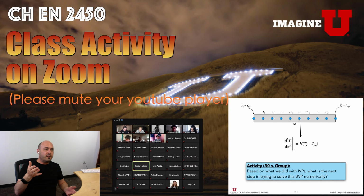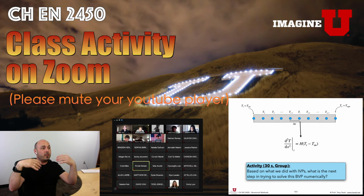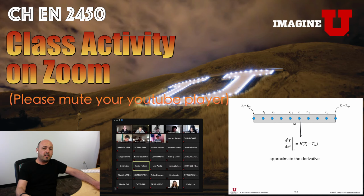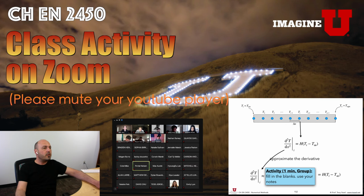So if I use finite difference, like Porter suggested, then we can untangle that derivative into a relation between neighboring points, right? Remember the finite difference derivatives? And once I have this relation, I can just apply it at each and every point. I will not have an answer. I will have the equation governing the answer, okay? So if we were to follow through with this, we just approximate the derivative. We say that d2T by dx squared is, fill in the blanks now, feel free to look up at your notes. What are we going to put in here for the second derivative? We're going to approximate the derivative with a relation that relates the points to each other. So look at your notes, go to the finite difference set of notes, and let's see what formula we can put in here.